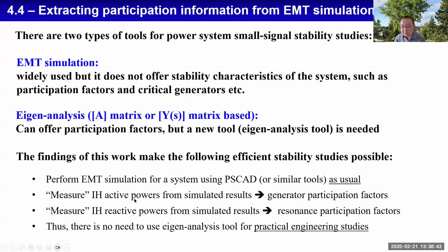Then we can measure the interharmonic active power from the simulated results, and you get a generator participation factor. Then you measure the interharmonic reactive power from simulated results, and you get a resonance participation factor. Therefore, there is no need to use an eigenanalysis tool for practical engineering studies.